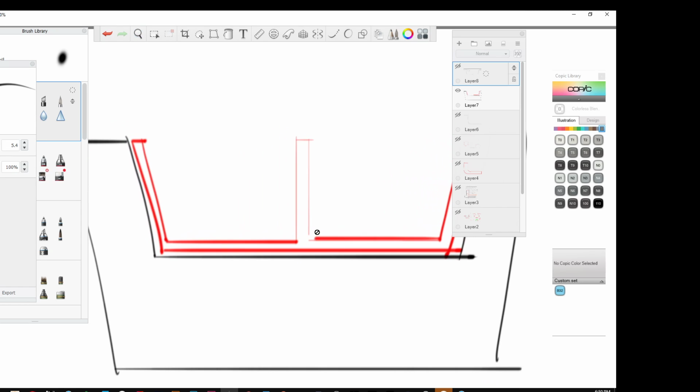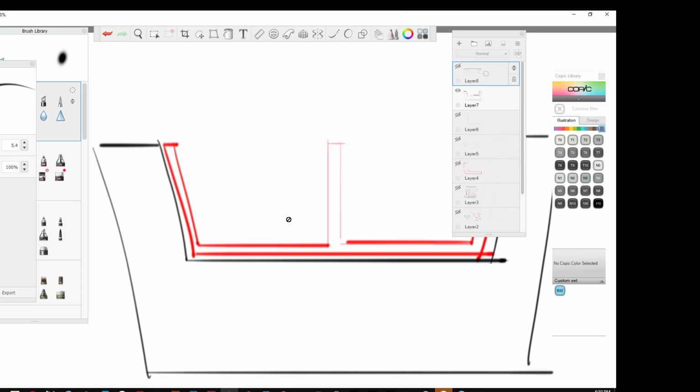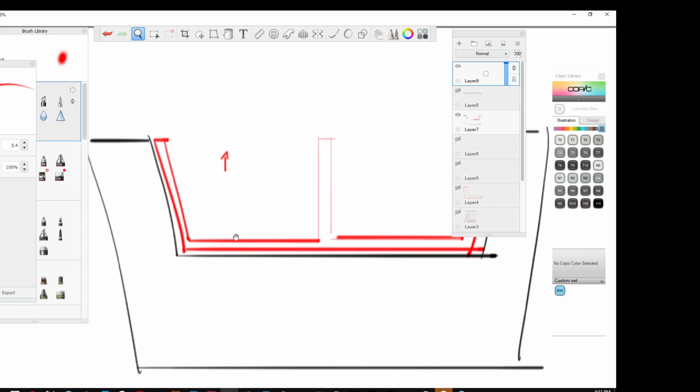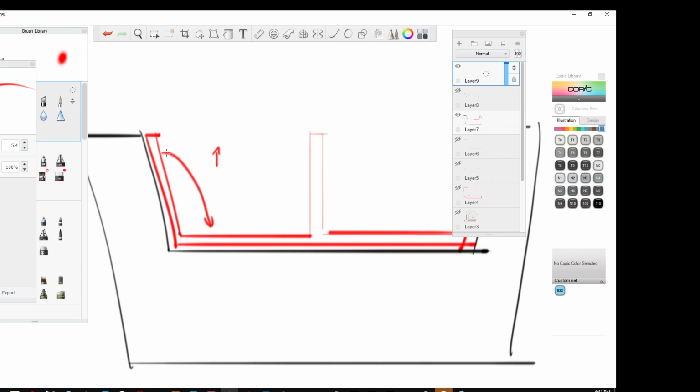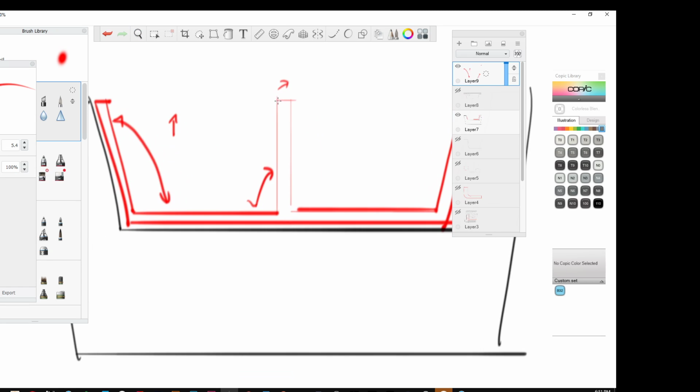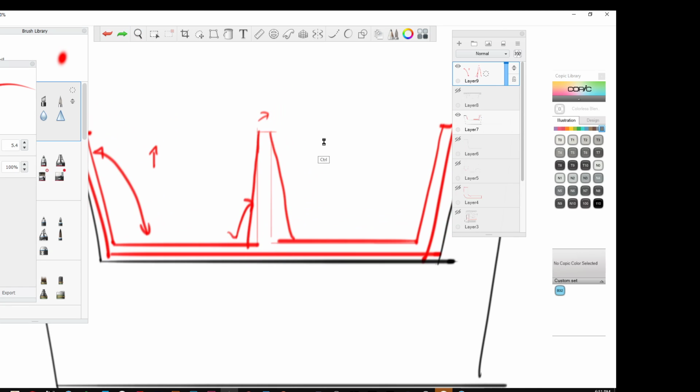you have to look at it as two separate parts or tools that go in to pull out. So if this is pulling out this way, we're doing great here because you've got that angle. But now this rib needs to be angled this way. So what you're going to have to do is angle it outward. That's really hard. Now the trick is, that's really exaggerated. You wouldn't have a rib that much. So let's say that's the 1 degree.